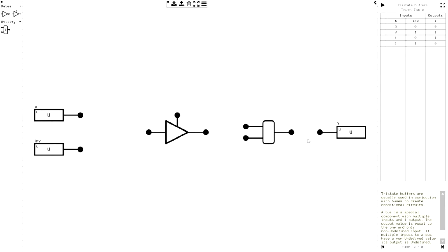So basically, I think the tri-state buffer is to do the outputs, the high outputs. I think it's to push out the high outputs. And the low outputs are to just go through the bus as normal, maybe? No, it can't be, because one of these inputs has got to be undefined in order for it to only take the one. Otherwise, if they're both not undefined, it will throw undefined out, which is not what I want.